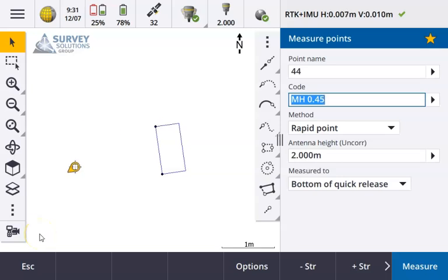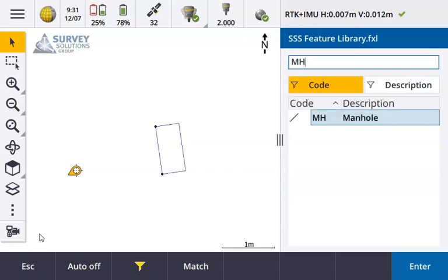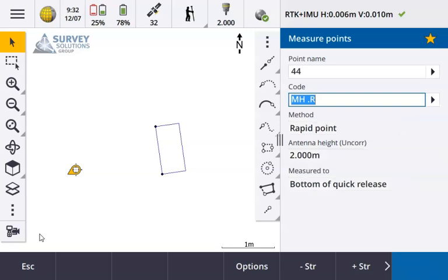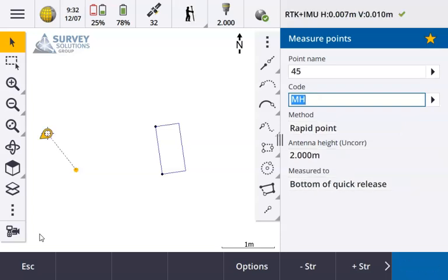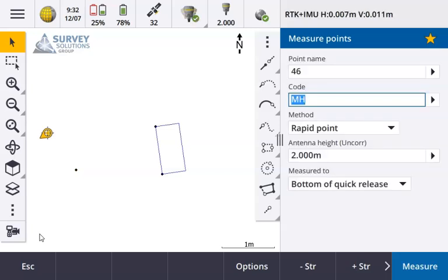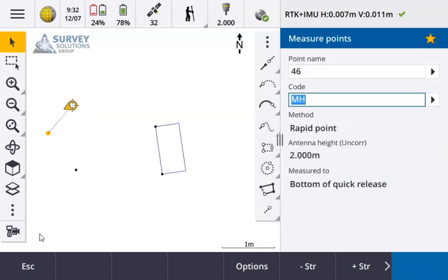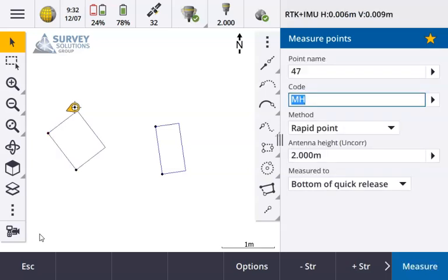To draw a 3-point rectangle, add .r, take your first point, take your second point without a control code, which it will automatically drop, and again your third point, and it will automatically draw a rectangle based on the information you've given.